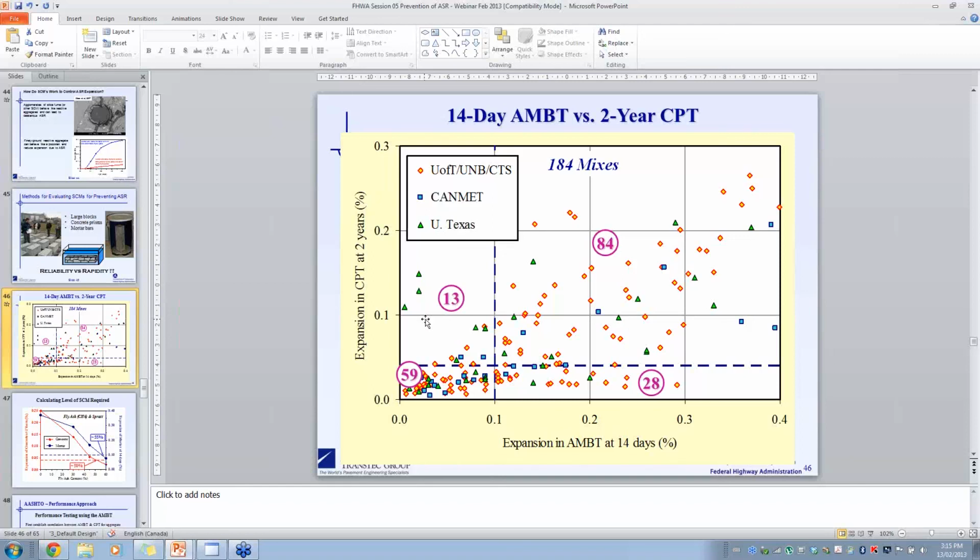We're talking about slag as a cementing material. I'm sorry that wasn't clear, but all the slides here with slag were referring to supplementary cementing materials. So that's ground granulated blast furnace slag. It's not slag aggregate. Slag aggregate would be a whole different issue.